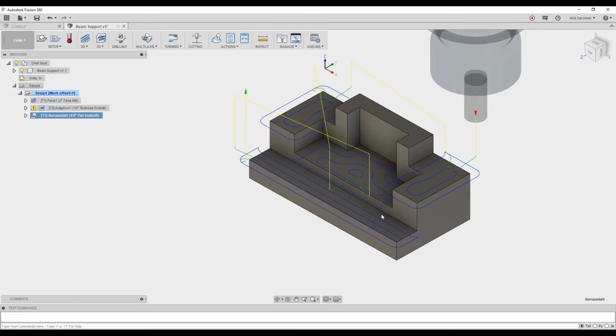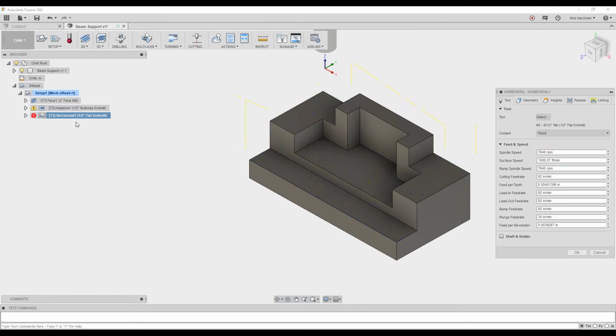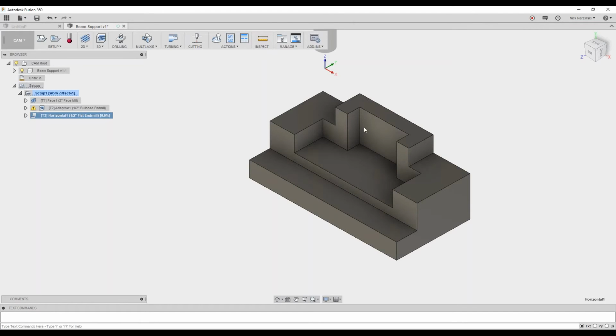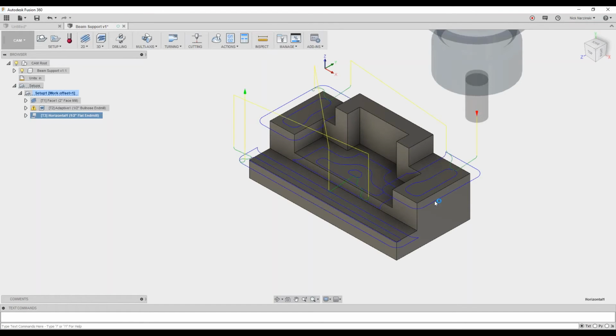The last thing that would be to come in and do a finish on our sidewalls. And actually, I meant to go back to that horizontal, and I wanted to leave that same offset on the side of the tool. So I'm going to say radial stock, 20 thousandths there, but axial 0. So that way I can come through with a tool path directly on the sidewalls and do a step down to prevent any type of tool deflection, or at least minimize the tool deflection.